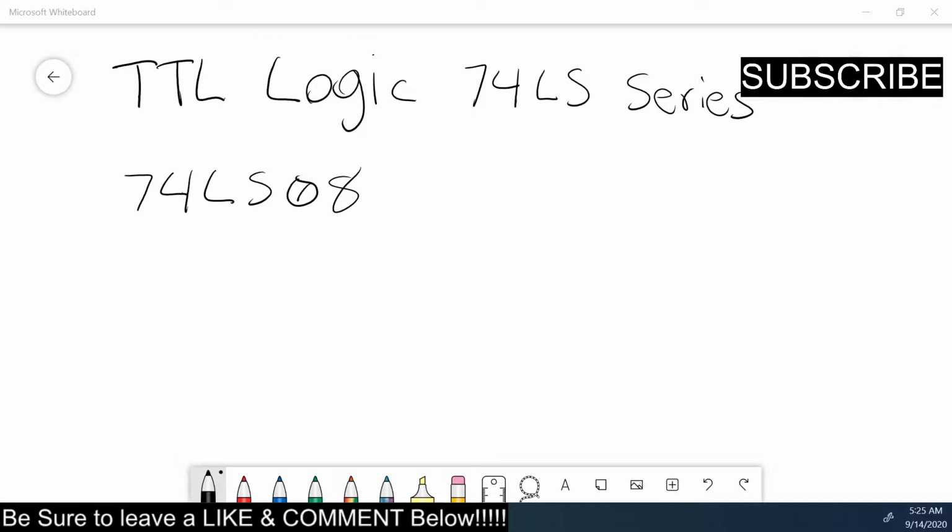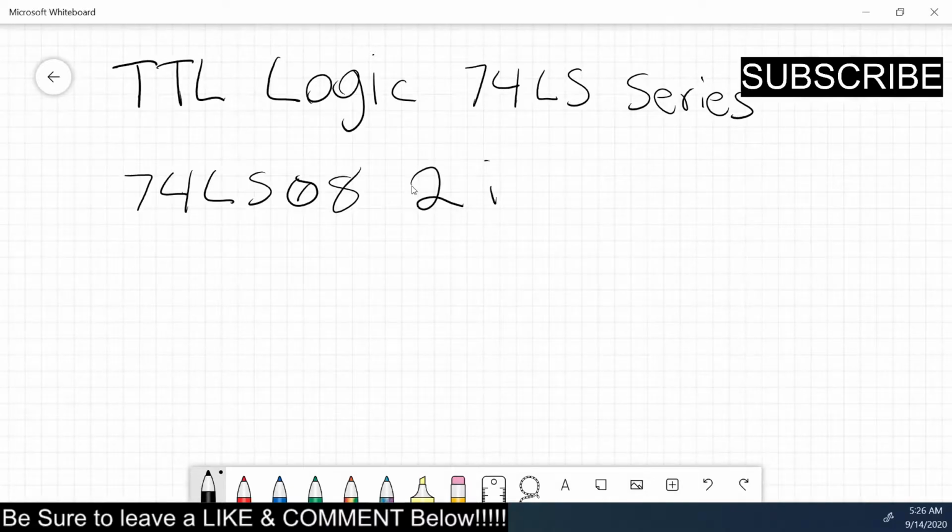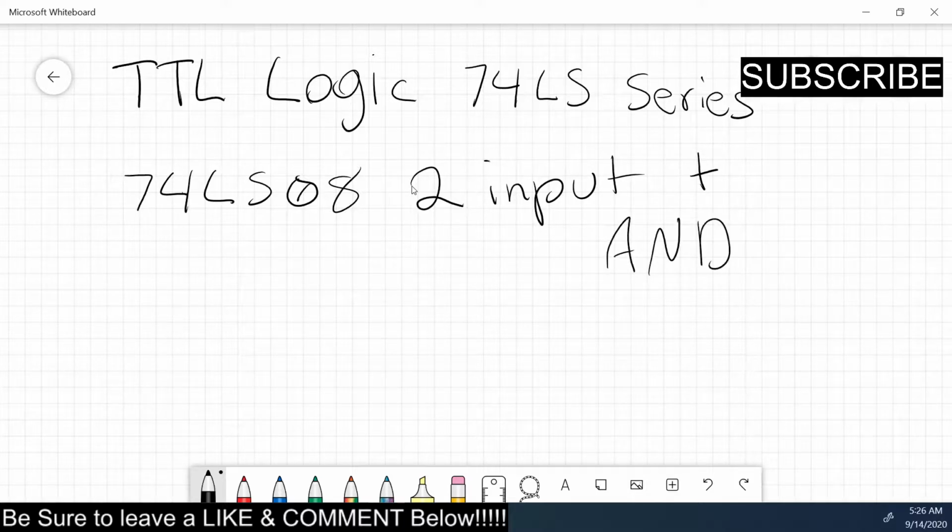We are continuing our look at TTL logic from the 74LS series. Today we have the 74LS08. It is a 2-input positive AND gate, and there are 4 of them, so it's times 4. So there's 4 of those on the chip.